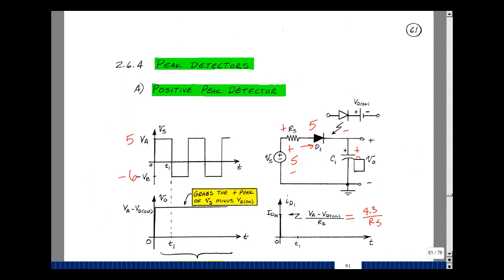Let's figure out where we're going to go. Wait long enough, where it's 5 time constants. What's the voltage across this capacitor? Well, in steady state, it's an open circuit, but it's never really an open circuit, just a big resistance. What that means is there's a little bit of current flowing. The drop across here would be VD on, or say maybe 0.7. Let's go around the loop now and figure out V out. Where's it going to go from 0 to what value?